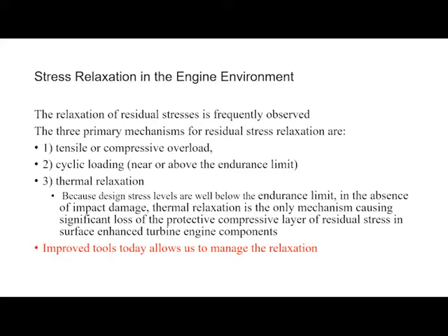And the good news here is as you can see, there's kind of three ways you can get that residual stress to relax. You can do a tensile or compressive overload, cycling, loading near or above the endurance limit, or thermal relaxation. And really for us, the main one is number 3, the thermal relaxation.